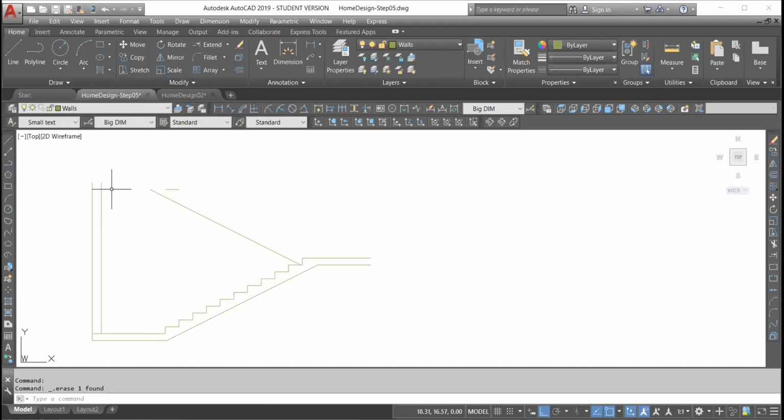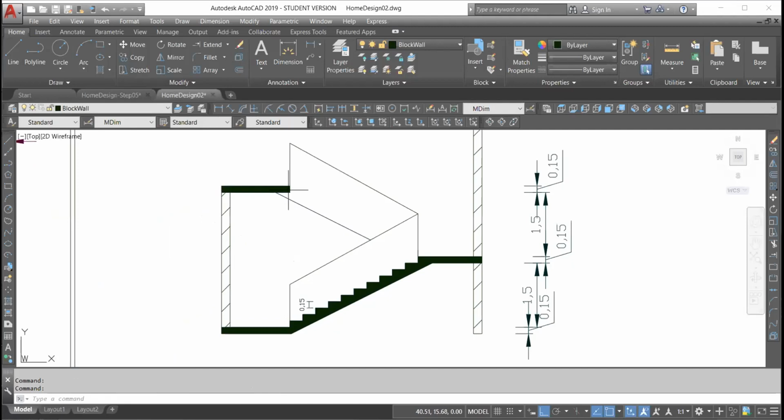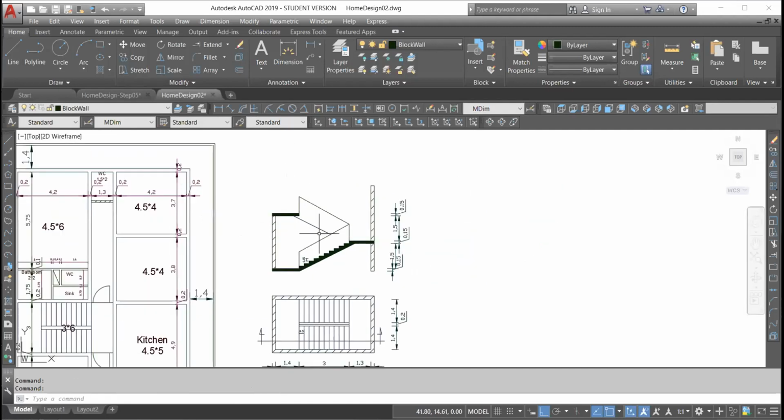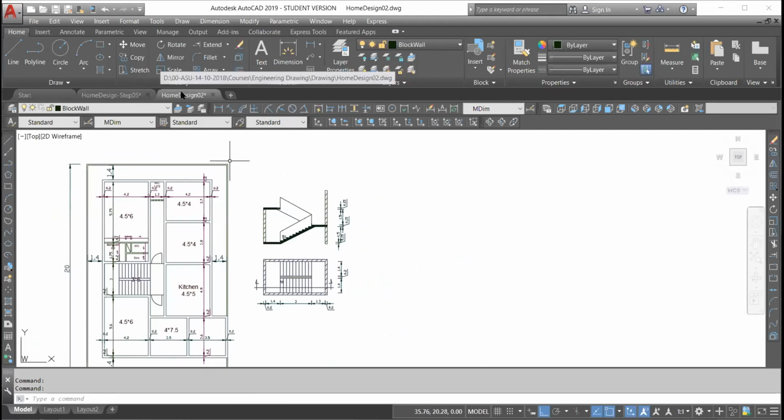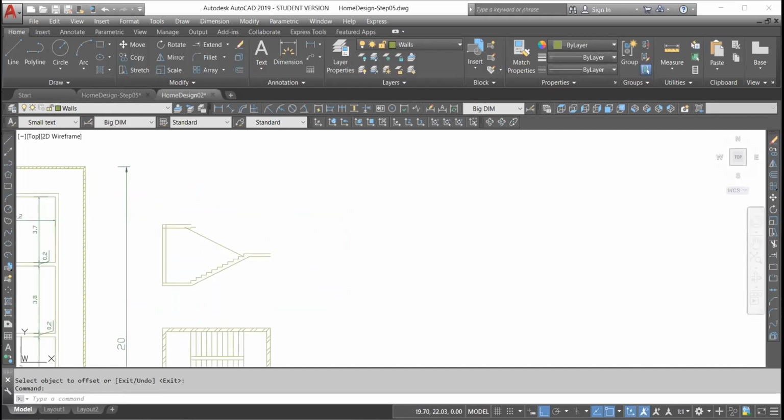Now from here I can draw the other side of slab, which is 1.6. Okay. I can make an offset 20 centimeter, offset distance 0.2. Click here, I click enter. So here, if you come here, you can see that I can see this shape. So please continue this drawing now. Try to draw it, okay, to complete it, arriving till this point.